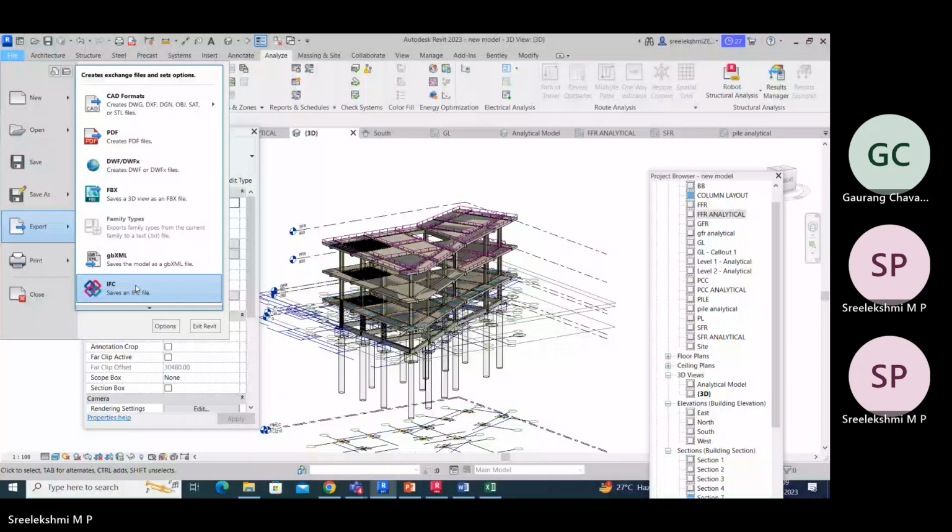That's not possible. But if you are doing a 3D model in Revit, we can insert an AutoCAD file as a reference, only a reference. Under Insert we have an Import option, so we can import a CAD file over here, but it acts entirely as a reference. Still, we can pick grids or lines from that drawing.